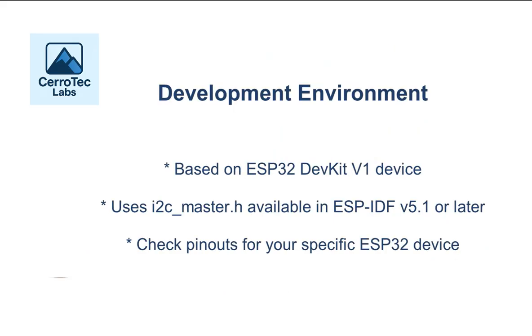Now a word about my development environment. I have developed this using the ESP32 Dev Kit V1 module. Please check your pinouts if you're using a different ESP32 variant. Also note that the solution presented in this video will only work with ESP-IDF version 5.1 or later.